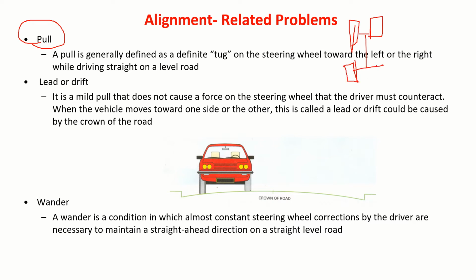While steering, the vehicle may start pulling towards left or towards right depending upon which wheel alignment angles are changed. There will be a real force and we have to counter this continuously using our steering system. So it will start generating pull. It may make the vehicle unstable sometimes.